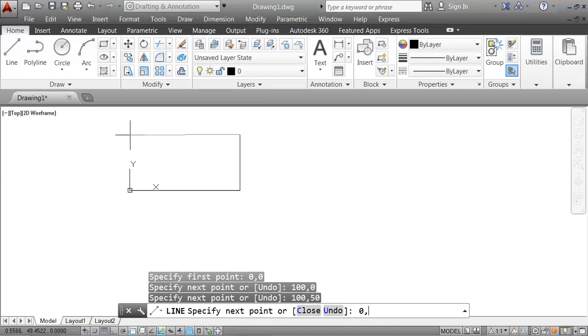You're going to go in the Y direction. What is the last point that you did in Y? 50, right? Last point that we did in Y, 50. Are you going below 50? No. Are you going above 50? No. You're going to remain at the same height of 50. It means just keep the same height of 50. And you click. This is when the line is not going to change the height, just remains at 50.